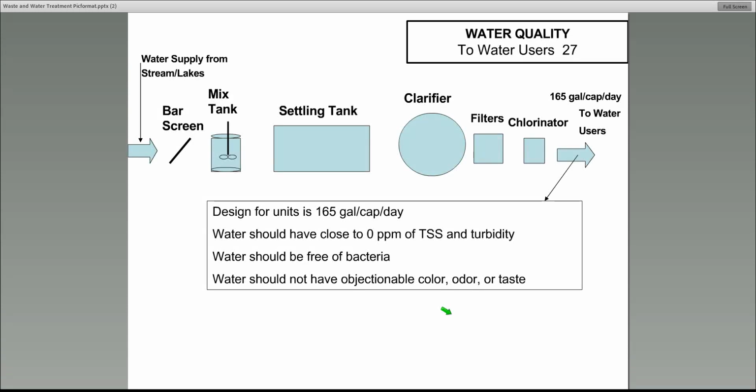Going back to the sand filter, it's required that you have a depth of at least 3 feet because the solids would break through if the depth were only 1 foot or 2 feet. It's been studied, and you need at least 3 feet depth of sand to keep the solids from breaking through.